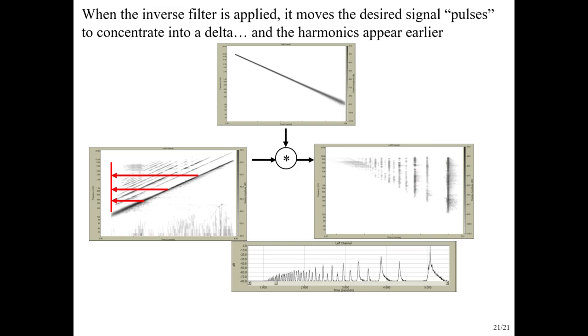And so what does that tell us? These are all of the impulse responses that we can use in a Volterra-based implementation if we wanted to analyze or simulate that system. So we don't need this when we're just trying to find the linear part of a room and all we care about is getting the nonlinearities of the measurement system out of the way.